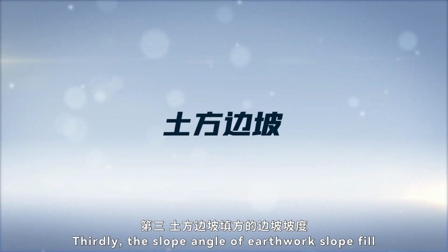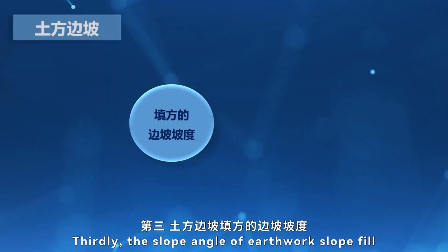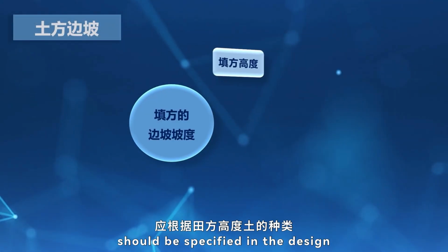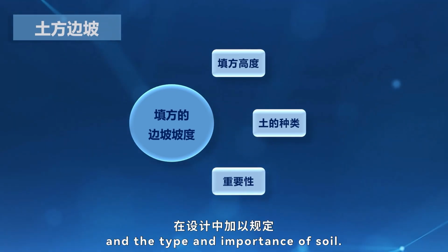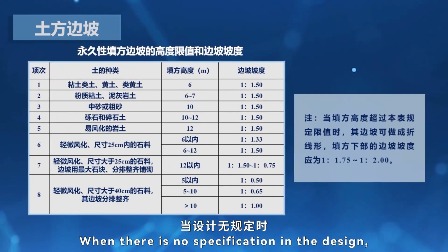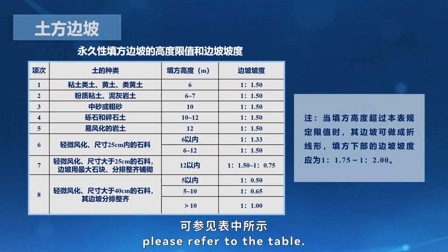Thirdly, the slope angle of earthwork slope fill should be specified in the design according to the fill height and the type and the importance of soil. When there is no specification in the design, please refer to the table.